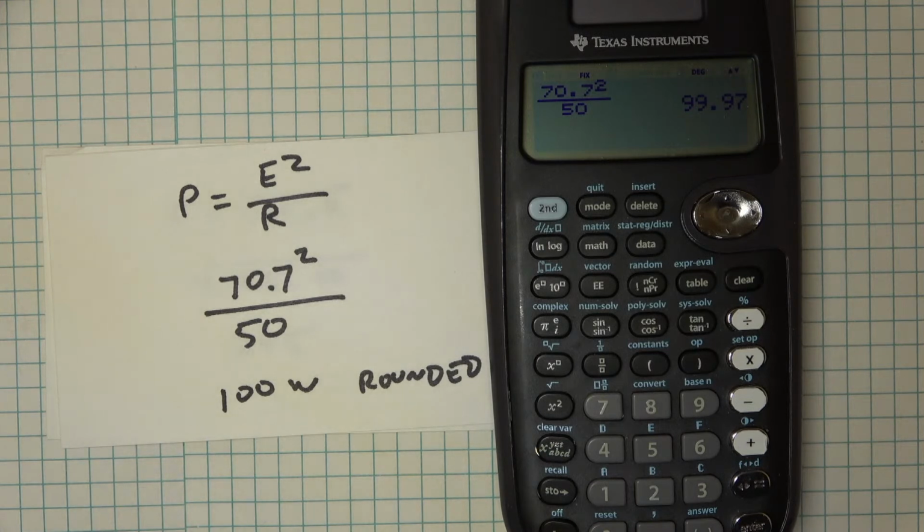So you're saying my 100-watt transceiver, when I transmit, is going to have 70 volts at the far end of the cable? Right, or actually at the output of the transmitter. All of the FCC PEP specs are at the output of the transmitter. Good point. So if you had a zero loss transmission cable, that's what would appear at your antenna.